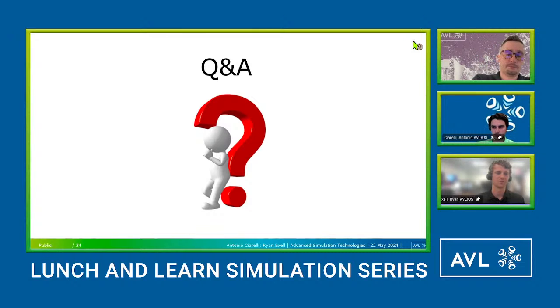Yeah, definitely. One of the times that we use FireM before we use PreonLab is for calculating the airflows for vehicle soiling. We start with the airflow in FireM, and once we have that calculated, you can easily import it into PreonLab and have a more accurate model where the airflow is already simulated, and then simulate the water with that as well.